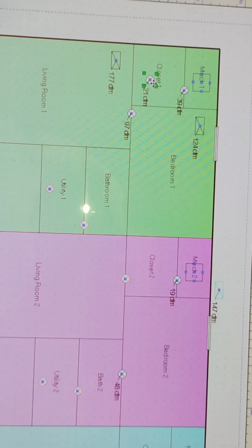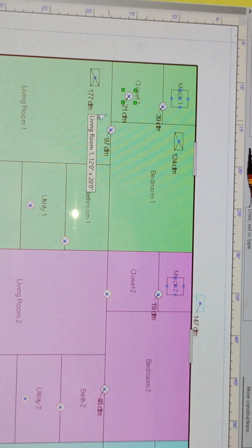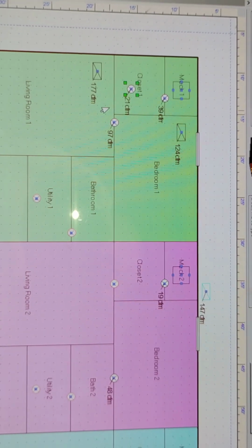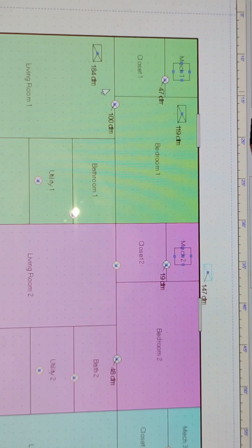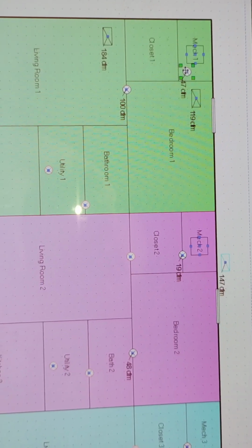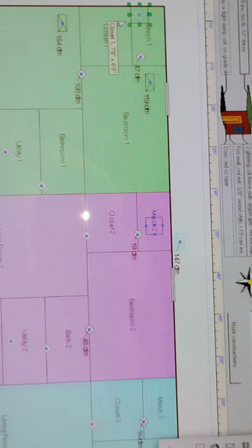Oh, this one's for the closet. 21 CFM really isn't enough to worry about, especially with the return and everything coming back by there. Going out underneath the door will be enough. So we're going to delete this grill, and that'll add it into our mechanical room, where we are going to leave air going into our mechanical room.